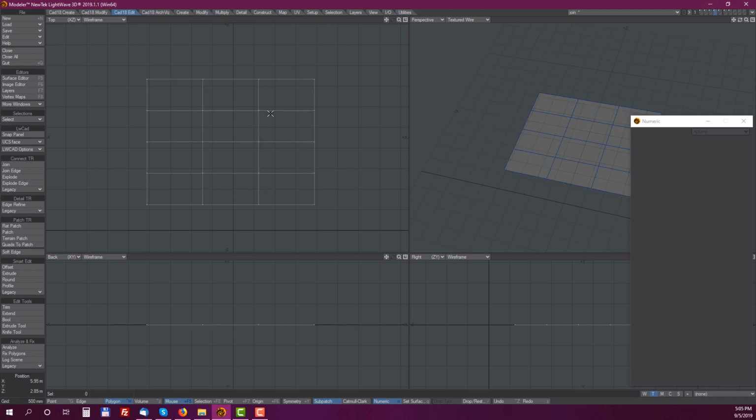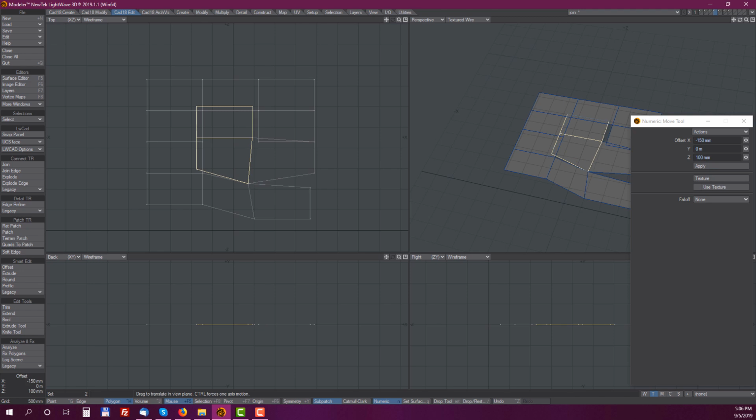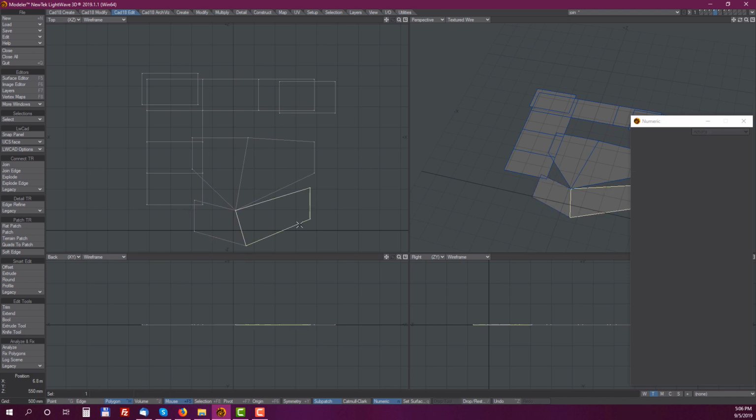Next, the fourth case is again several quad polygons, all separated. In this case, I will show you how it might be useful to use join edge selection. So I will join only these two edges, and the result is, if I move this polygon, you can see that only these polygons are merged. So all other polygons are separated, and only these 4 polygons are merged over selected edges, as you can see in this example.